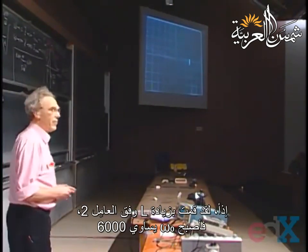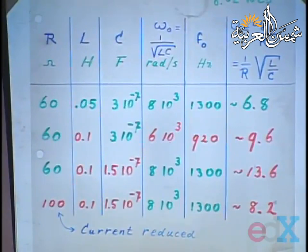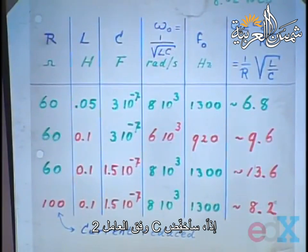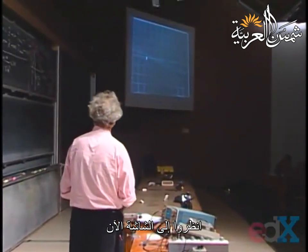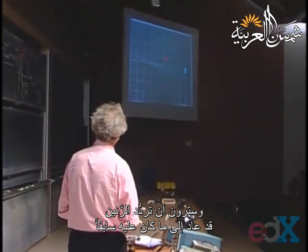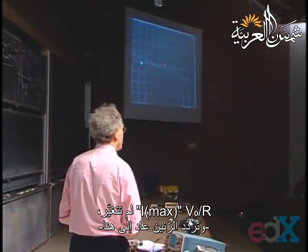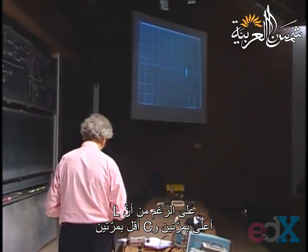So I have increased L by a factor of 2. I can bring it back to my original resonance frequency by now changing C. If you increase L by a factor of 2, all you have to do is decrease C by a factor of 2, and you're back at the same resonance. So I'm going to make C lower by a factor of 2, which I'm doing now. And if you look now here, and you have a good memory, you will see that the resonance frequency is back where it was. Again, V0 over R is not changed, and the resonance frequency is back here, even though L is now twice higher, and C is twice lower.